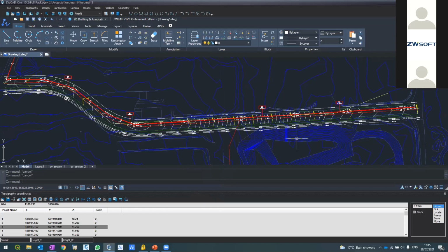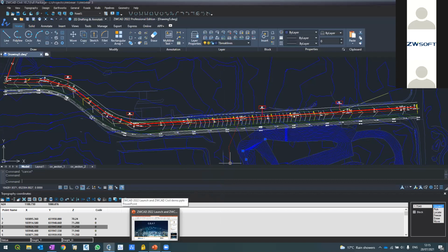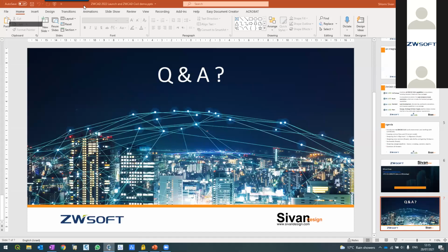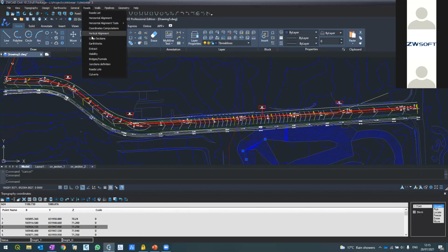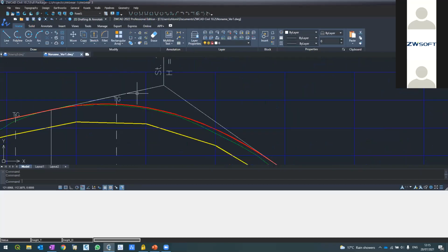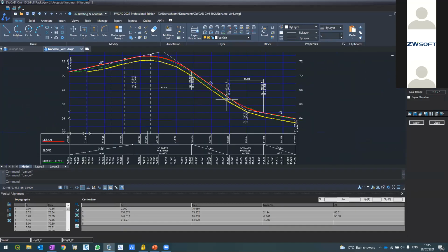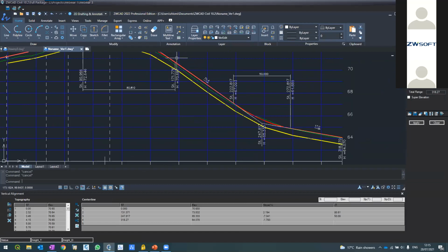50 meter, why 50? Why not 70? What guides the 2T? In this case, I used 50 because I looked at the curve, and this is what guided me in terms of visibility. Look, this is a small road, and I used 50 meter because I wanted a curve that does not intersect here on this distance.